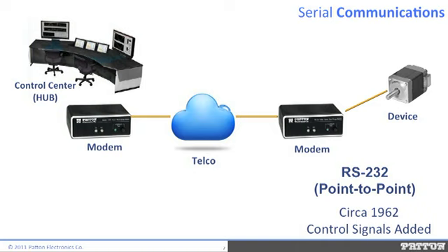In the industrial environment, RS-232 is used in two main applications. One, in the use of dial-up modems for making a temporary communication channel through the telephone company over longer distances. And two, in simpler scenarios needing the use of short-range modems or interface converters that operate over private dry copper lines. Due to the nature of these applications, the distance is short and they operate with low data rates.